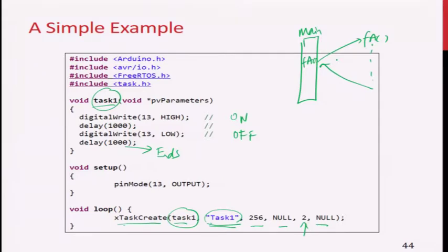But a task is not a function call. A task is created to run as if it is owning the whole CPU to itself. So if I create a task that is only going to do these 4 lines, you will do these 4 lines and that's the end. There's no returning back.